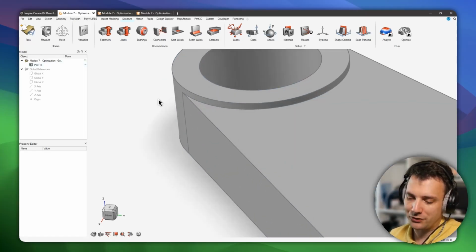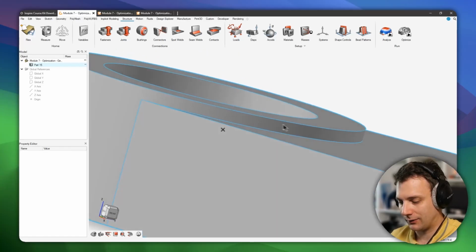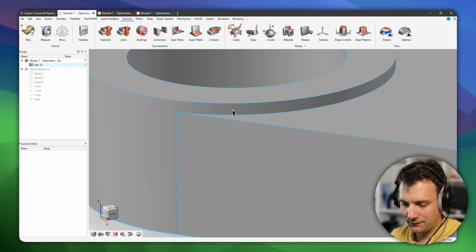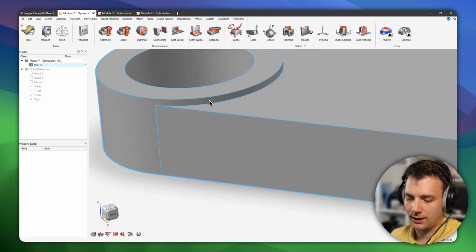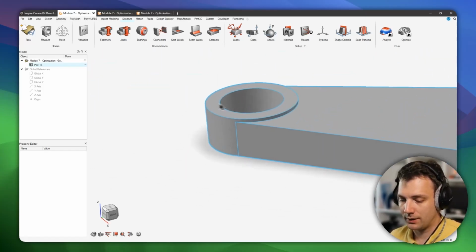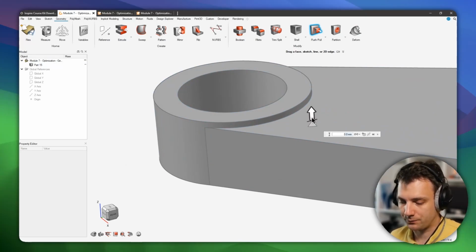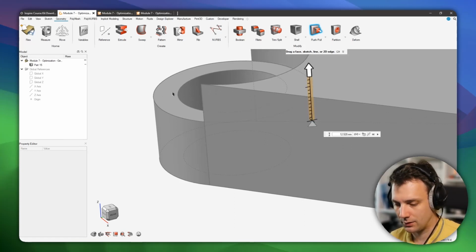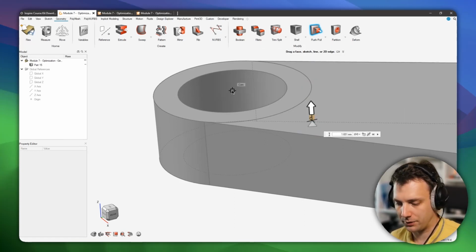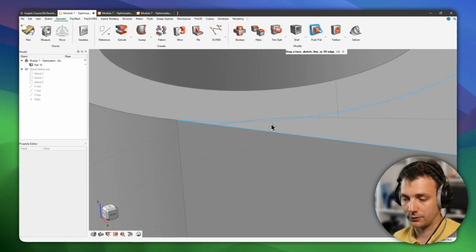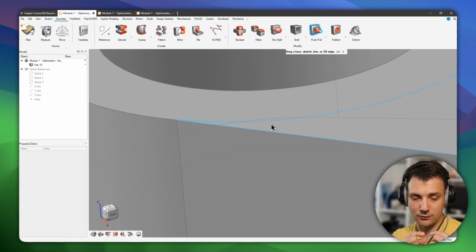Some things that can bite you in the meshing process are those little gaps or steps, or whatever you would call them. These small features could cost you, and you can get rid of them pretty easily. If I had to topology optimize this, I would do just a push operation, click on here, and then drag it to a point on the surface area. Basically the center would be the one I would pick, and then let go, and you're done. So this gap is removed, and it's easier for the solver to mesh it, because there's no need to create little elements there because of the geometric feature.